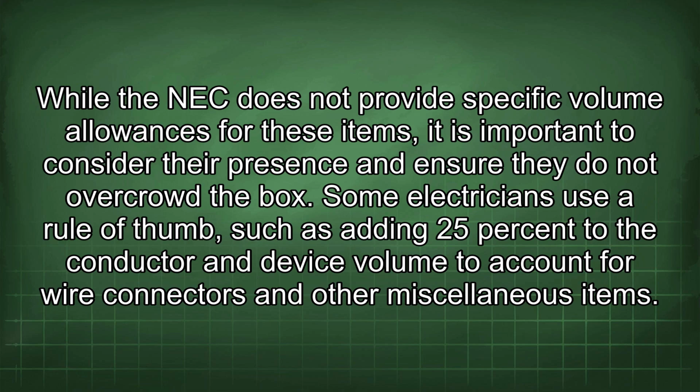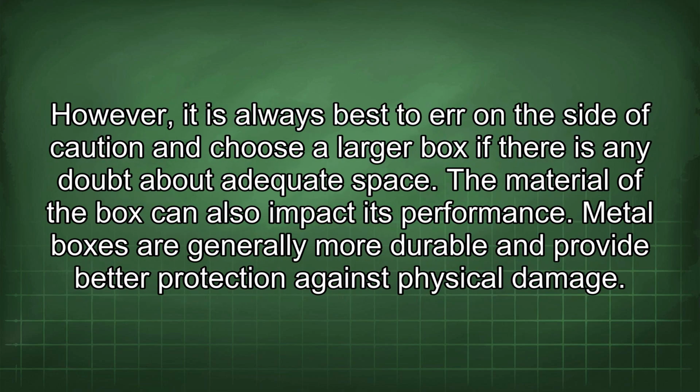Some electricians use a rule of thumb, such as adding 25% to the conductor and device volume to account for wire connectors and other miscellaneous items. However, it is always best to err on the side of caution and choose a larger box if there is any doubt about adequate space.